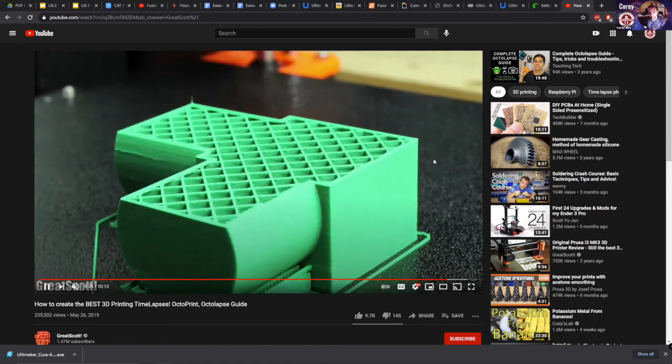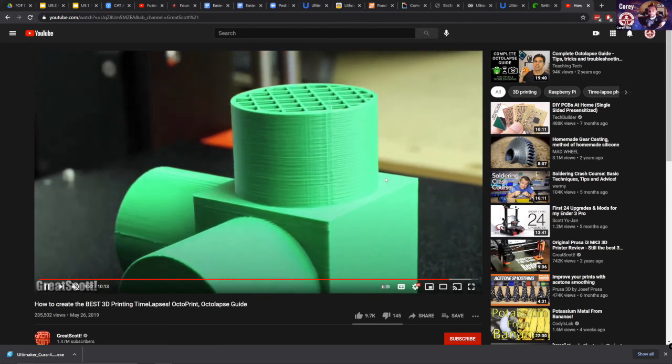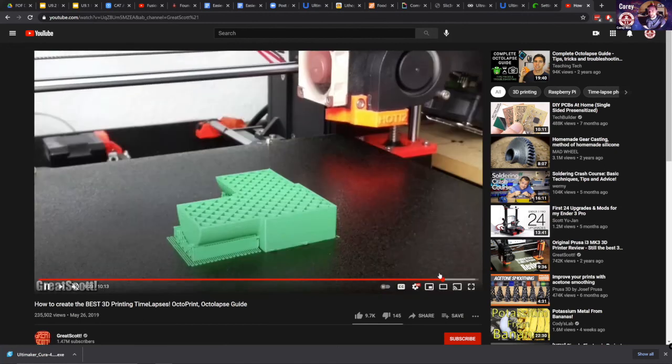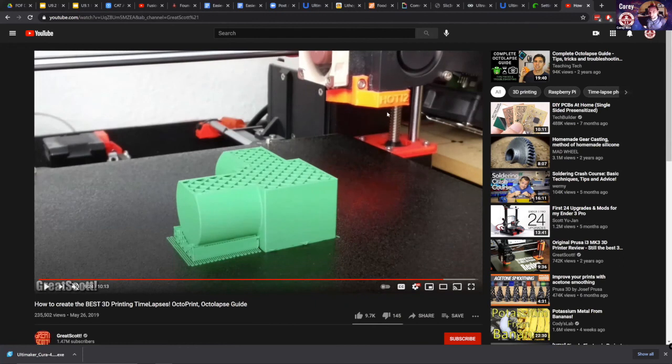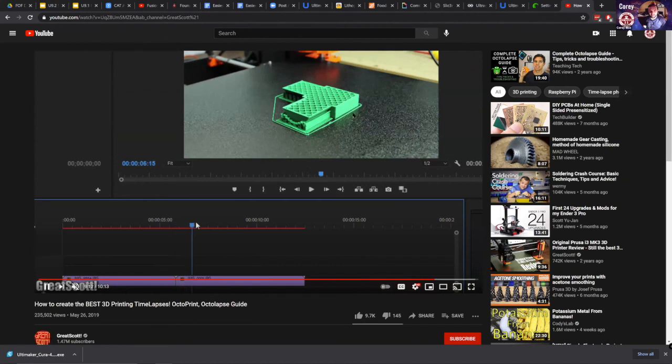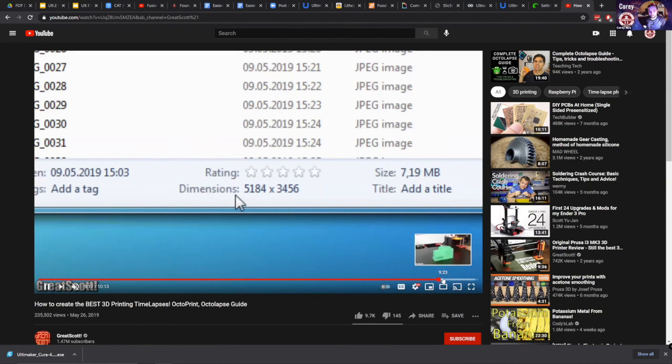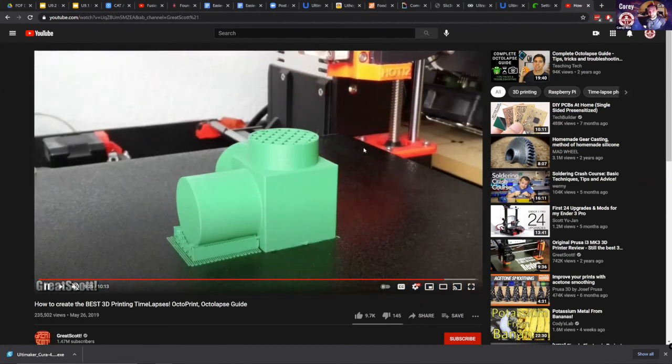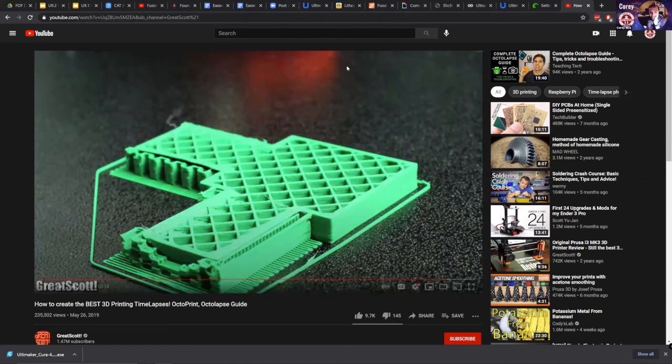If you want to do an Octopi time lapse, here it moves the print head out of the way and then takes a picture. It has to change the G code to do this because you can see the extruders over here on the side, but the G code moves the print head over, and then with the G code, it says take a picture. So it always takes a picture with the print head in the same location. So you don't have like a time lapse where this thing's zipping all over the place. It just moves out of the way and it's always in the same spot. So your time lapse has the thing moving up along, and here he's editing. Is that many photos? Yeah, but it looks like this. And if you can figure out the camera, I'm sure lots of people will love you at MakeHaven.